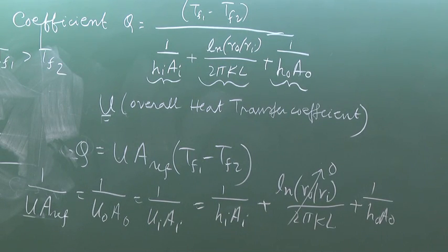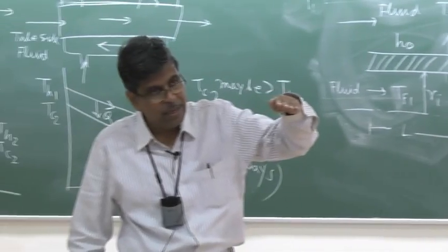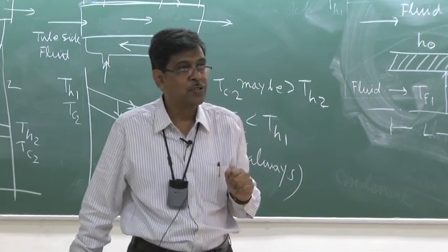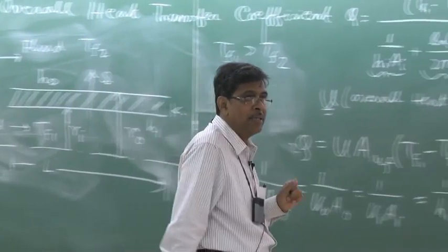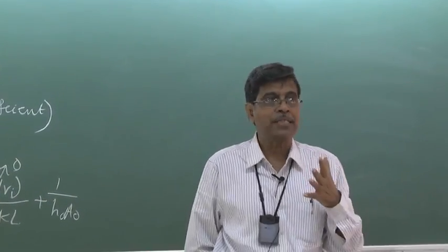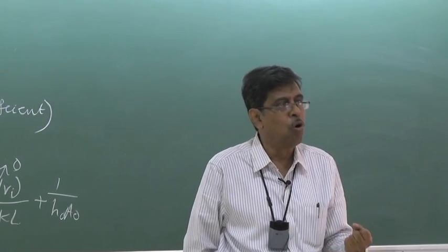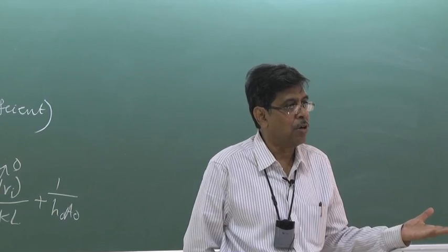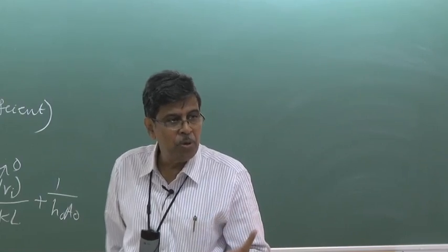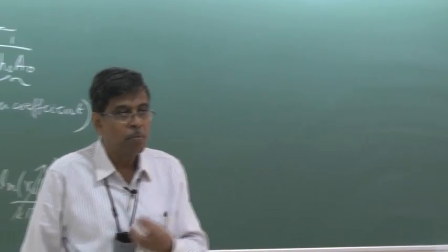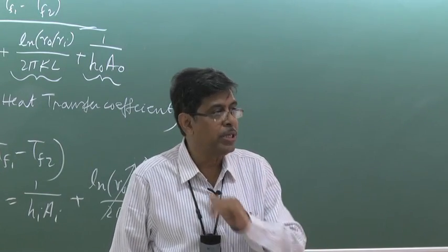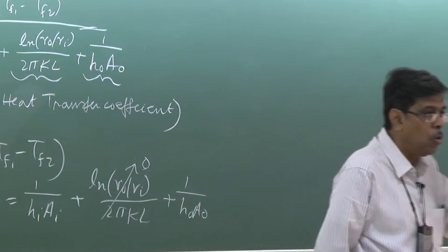Here also the heat transfer takes place from one fluid on the inner side, let us consider the hot fluid, to the outer cold fluid via the tube material, the solid tube. Now another thing is there which is known as the fouling factor. These are all practical things, but we have to know them as information. After a long operation in industries, usually the impurities in the liquid flowing on both sides, either tube side or shell side, get slowly deposited and make a coating in the form of a film over the two surfaces.